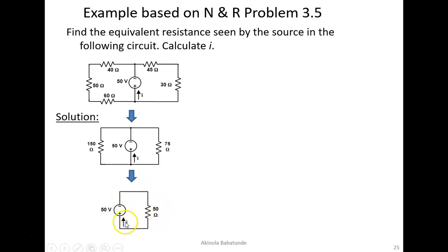You will notice that the current is actually leaving from the region of low concentration and then going through the circuit to the region of high concentration. So the polarity is going to change. In the first case, it's supposed to leave from the region of positive, high concentration to low concentration, but now it is leaving from the region of low concentration, going to the circuit element and then back to the region of high concentration. In this particular case, the current is going to be negative.